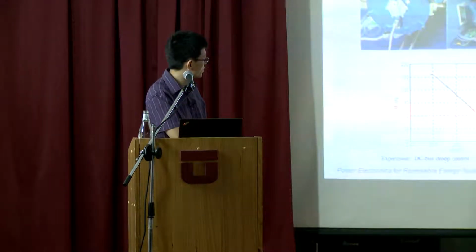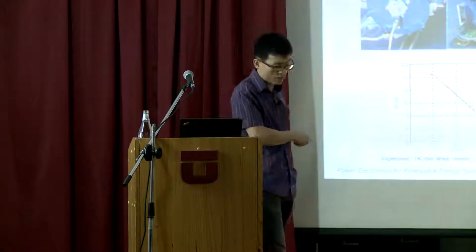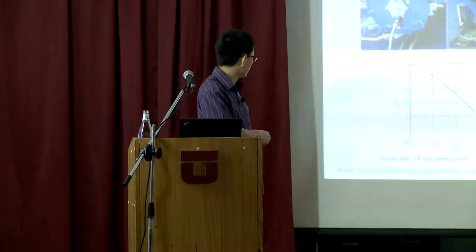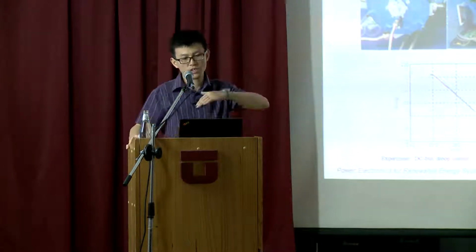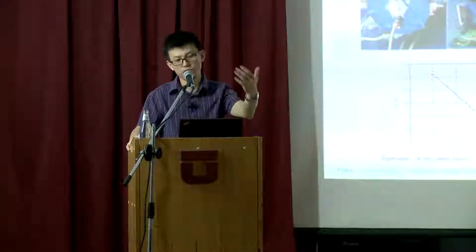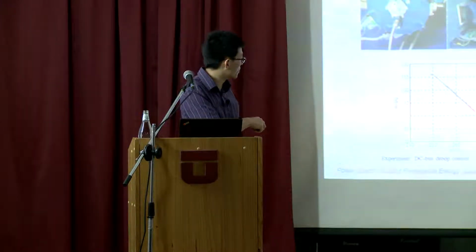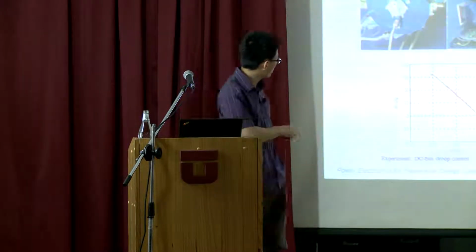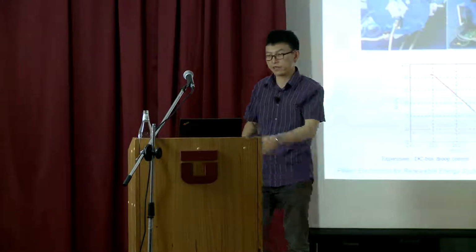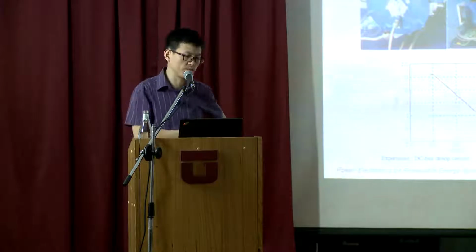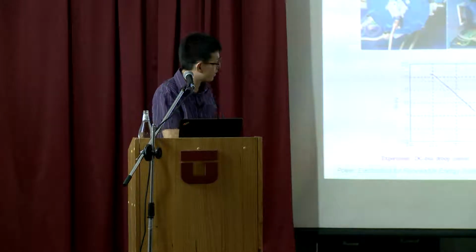You see this droop curve. So you have the voltage and the current. This is the voltage and this is the current. The VO somewhere is 270 volts. So I have voltage change, and the system supplies power or current to the load. So this droop concept, and all the information, I think you can see very clearly. There are lots of dots on it, and it's actually from the experiment results. We just line this up and match with what exactly we wanted it to deliver. It exactly follows this droop characteristic.